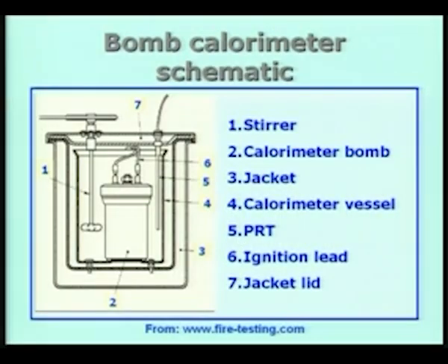And the bomb is filled with, as I said, pure oxygen at about 25 bars. The reason why we want to fill the bomb with high pressure oxygen is to see that the reaction is going to be complete, the combustion reaction is going to take place completely. That means that the entire specimen, the entire mass of the pellet which is taken inside, is going to completely burn, and the combustion products are going to be formed from that.